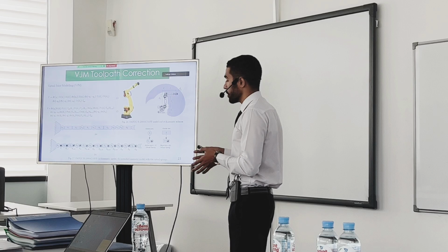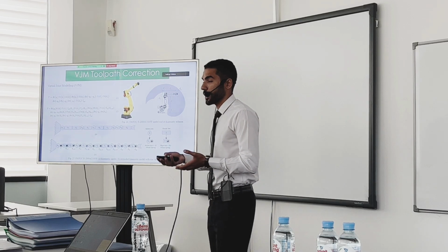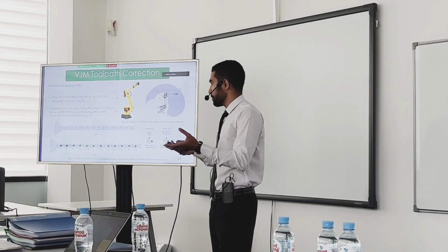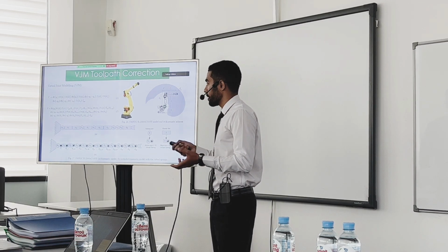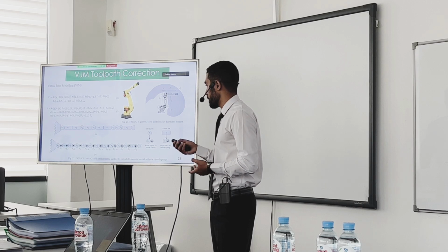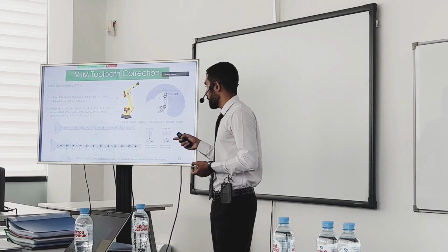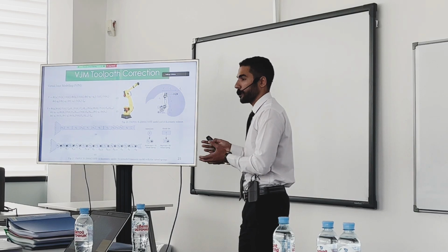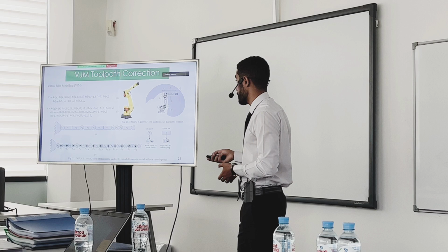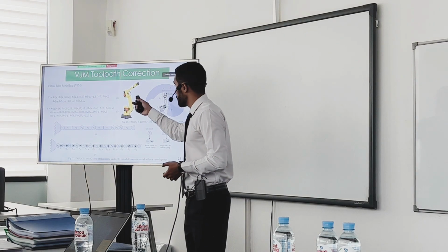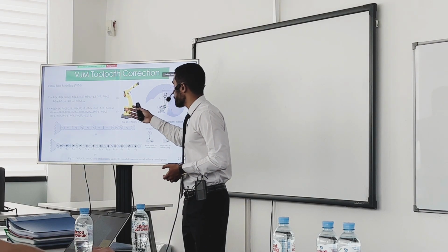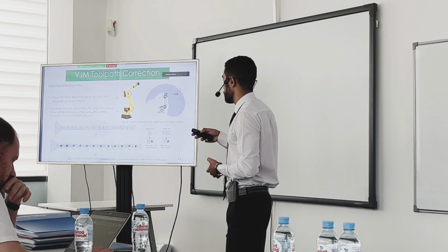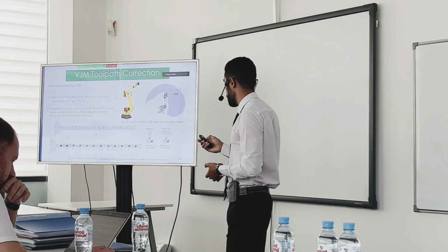So in virtual joint modeling, you extend your kinematic chain with virtual springs. For example, the joint would be extended by only one degree of freedom spring, and the elastic link will be represented by a rigid link plus 6 degrees of freedom virtual springs. That's why the transformation for the forward kinematics becomes more complex by adding these virtual springs.